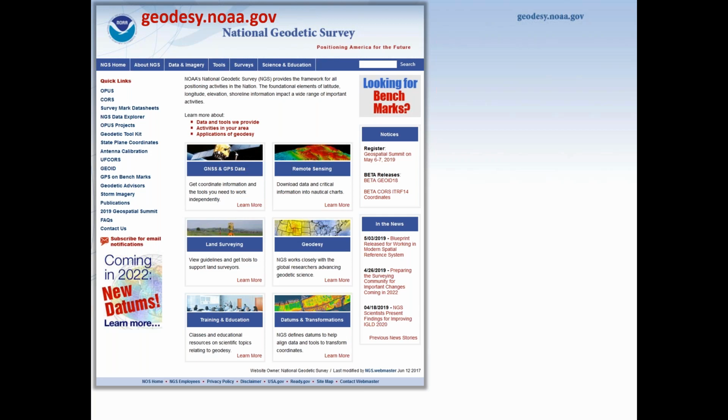There are actually 3 NAD 83 frames simultaneously: one for North America, one for the Pacific Plate, and one for the Mariana Plate. People just say NAD 83, but really there are 3 different ones, and they are different. Part of that is just perception and history. Why call Guam North America? It doesn't really make sense, but it inherited that name because of the way things have evolved over time.